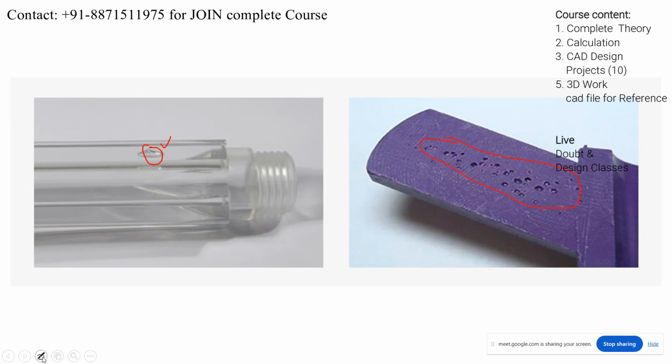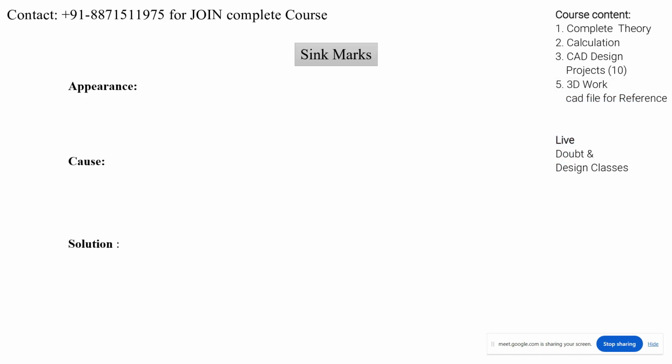Right? Similarly, if you are dealing with HPDC, there we use the term porosity. And here, if we are dealing with the injection molding process or plastic components, we say voids, or bubbles, or air pockets, right? Okay, so here you can see that in the transparent component it is visible, and in the colored component it is not visible, right?